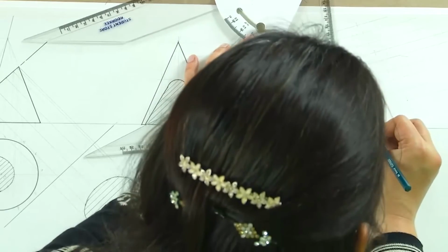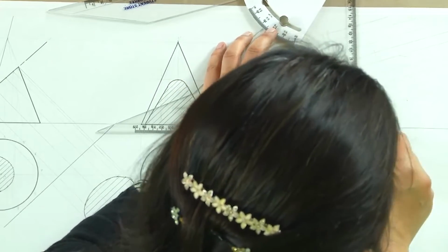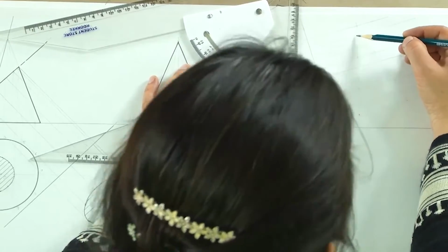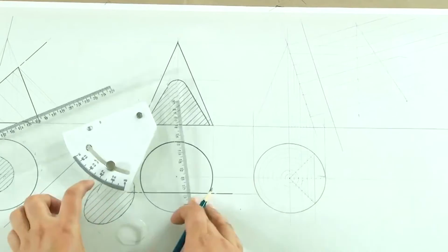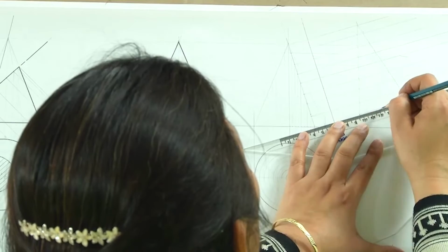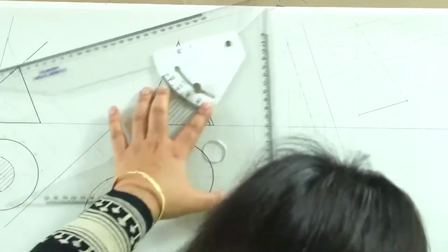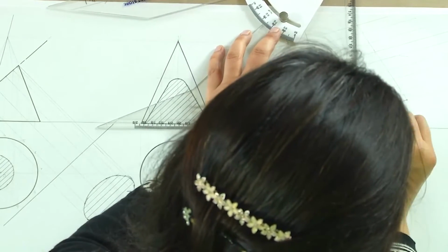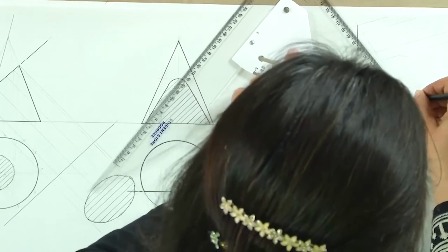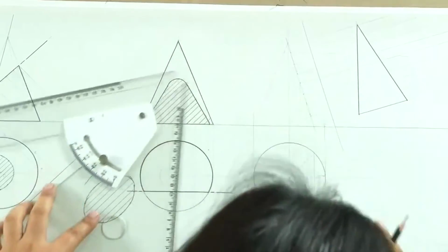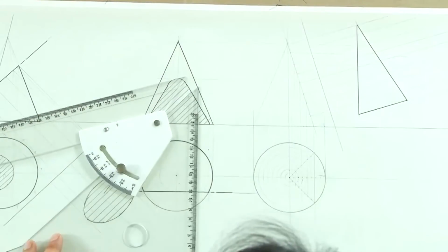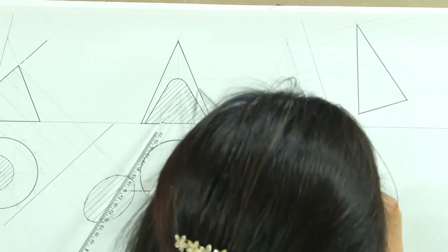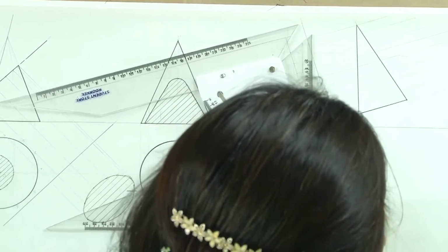Now, these are all the points that we would have got. If I try to connect this as a straight line, I am drawing a very thin line, we will see that there is a slight difference in all these points, but it is more or less the same straight line which is what we are going to get here. So, if it is passing through the apex, this is the kind of shape we are going to get. This is the true shape of the section which we were not able to see either in the front elevation or the plan. In the plan, we will only be seeing this triangle and the rest of the base.